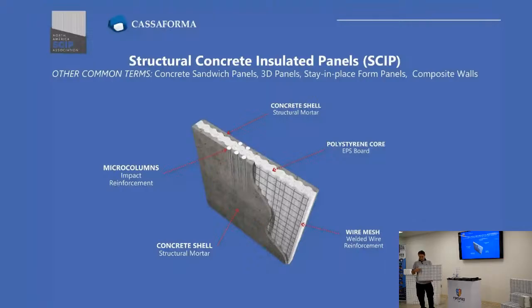So the other thing is that the wires will provide us with the strength for traction, for pull. So that's what the mesh provides. Then we have these guys here that run from one side to the other. We call them connectors, and that's what means that the two sides work together. If not, I will have just one side and another.